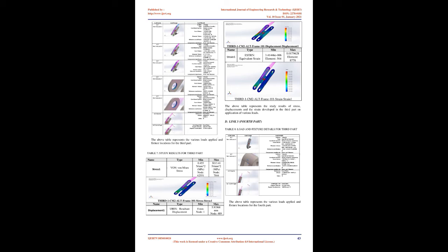With SolidWorks Simulation added in, one can perform multiple analyses such as stress, factor of safety, or deformation analysis of components. This can be done without fixing loads and boundary conditions. The required loads are obtained automatically from a calculated study. One can use the stress analysis results to display the consequences of motion loads on deformations and stresses for one or more components.